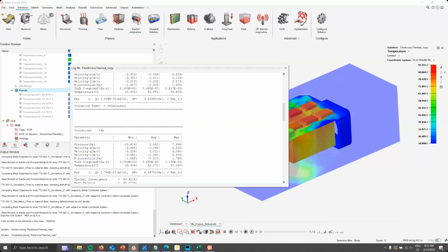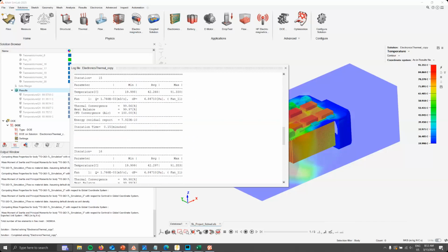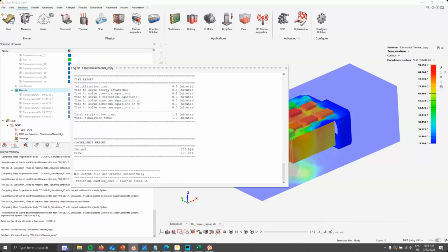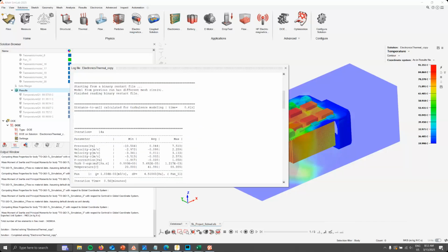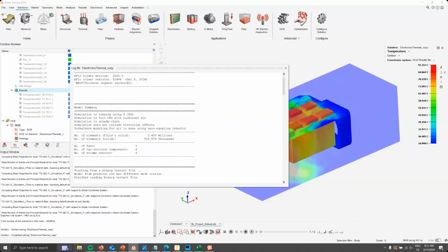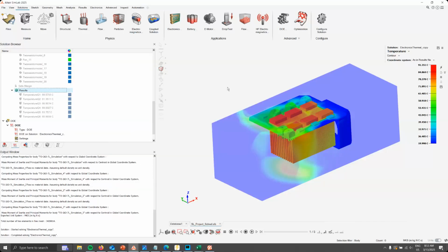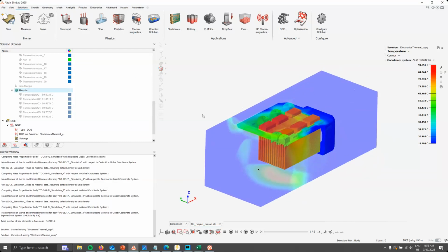So this iteration, 0.6 seconds, this other one, 0.6, 0.15. And this is the one that I just started by using the results file, right? So the previous one might have taken a bit longer, but this one took far, far less. So that's a great way of restarting a simulation by using what we already did.